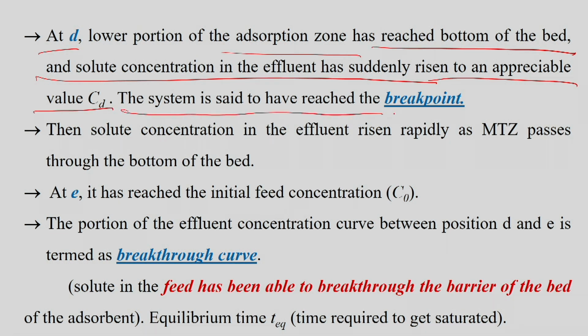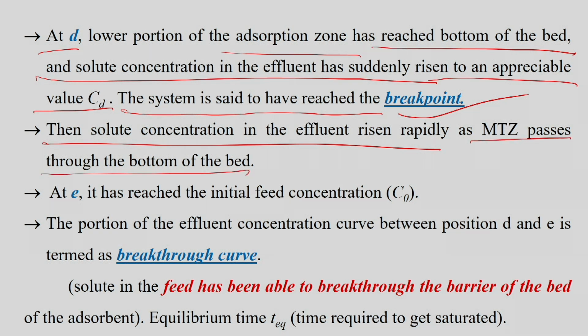This system is said to have reached the breakthrough, this break point. It indicates that in a small period of time the entire bed will be exhausted, then the solute concentration in the effluent rises suddenly and rapidly as the mass transfer zone passes through the bottom of this bed.